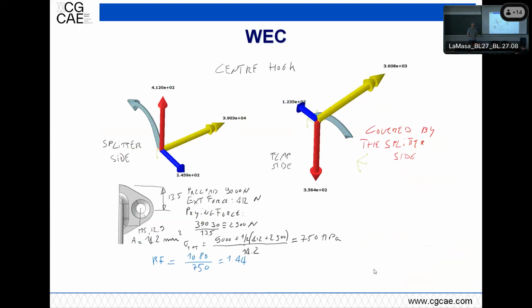And this was just to show that finite elements are fantastic. They give you tons of information. And sometimes, maybe more often than what is shown here, you still do some hand calcs because it's anyway a good approach. And you do it maybe based on the information you get from the finite element model, like in this case on these hooks which are connecting the wing to the flap. So the software can integrate the stresses on the section and calculate for you the section forces like that.